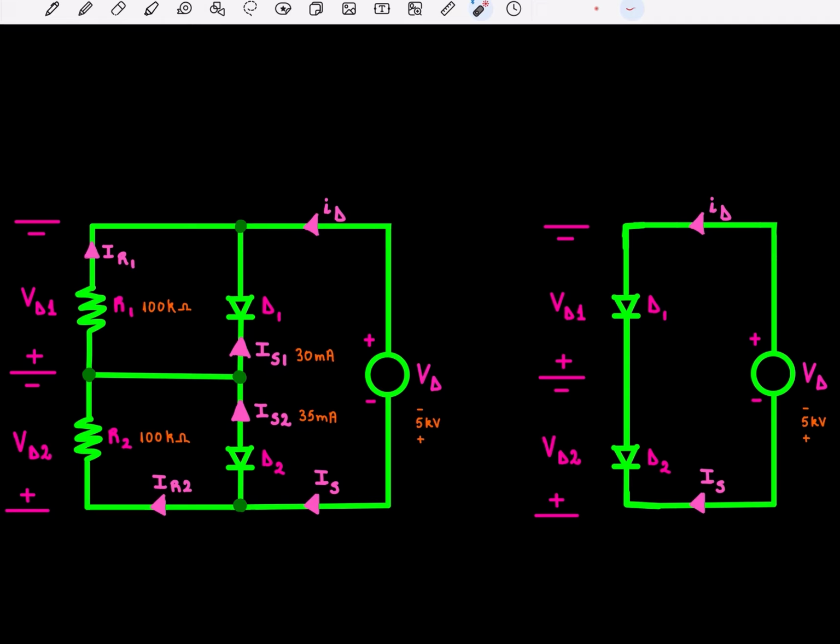when you have current flowing this way, in reverse bias, you basically have blocking voltages because the diodes withstand the flow of voltage. And due to manufacturing tolerances, the blocking voltage of each diode will be different. Each diode will carry the same leakage current. So when you're in reverse bias, you have some leakage current that still manages to flow through the diodes, and you also have blocking voltages.